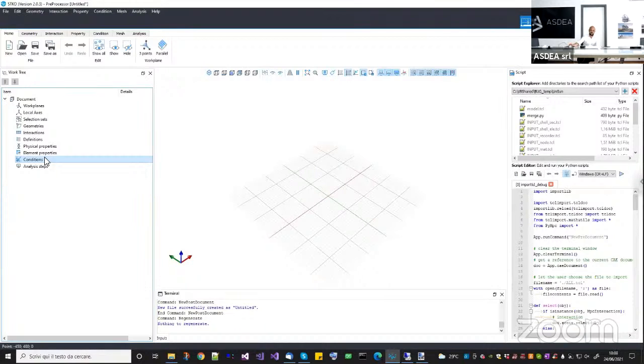Now, the problem is that in OpenSees, this kind of constraint cannot be added, because if you're familiar with OpenSees, constraints such as equal DOF or rigid links typically have one master node, so one retained node, and many constrained nodes. But in this kind of constraint, if I want to say that the displacement of a node is the weighted average of the displacement of many other nodes, it means that I have only one constrained node and multiple retained nodes. And this is not possible in OpenSees. So that's why I decided to implement it as an element.